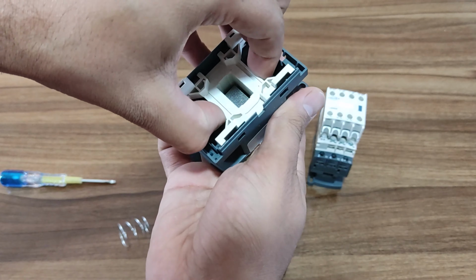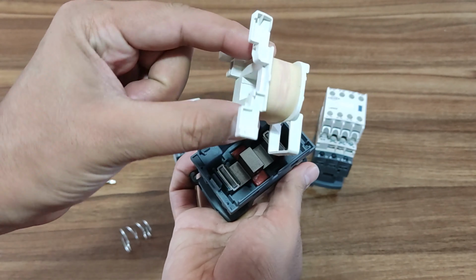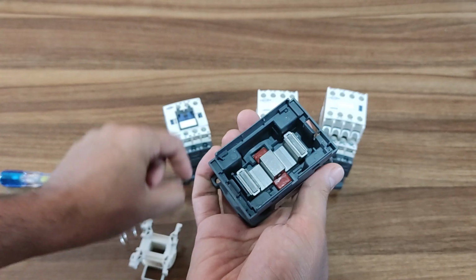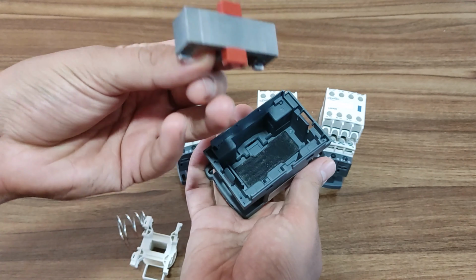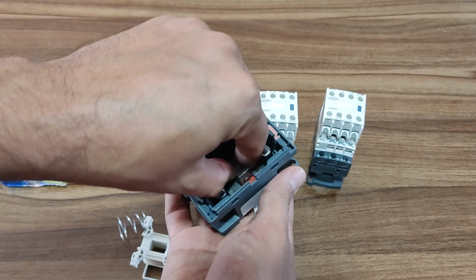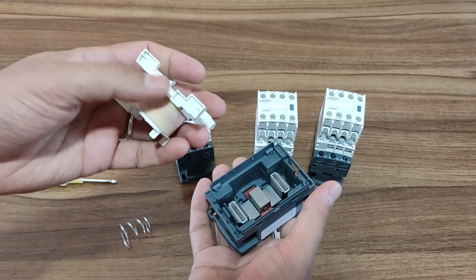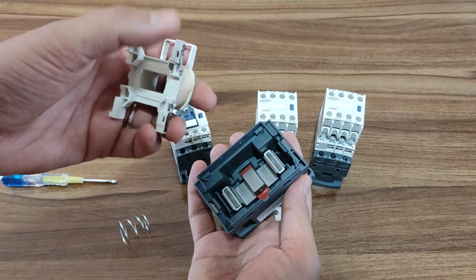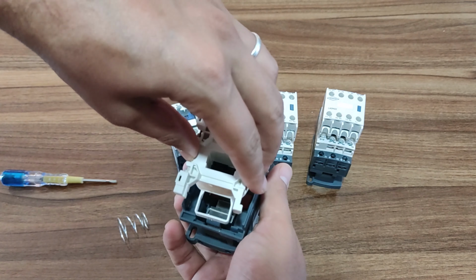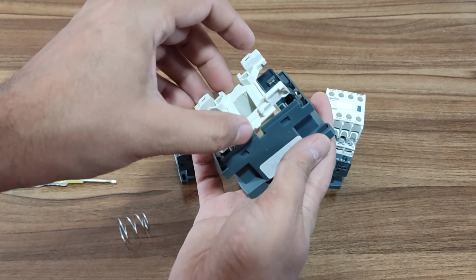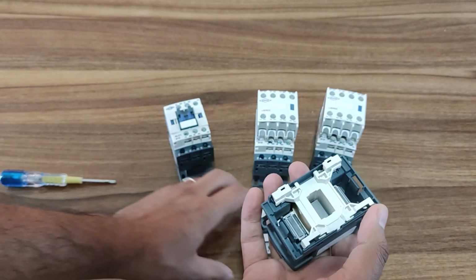Contactors are used in control circuits to connect and disconnect the consumer's power circuits. Contactors are actually the link between control and power circuits. These devices consist of two E-shaped cores, one of which is fixed and the other is mobile. Between these two cores, there is a magnetic coil or bobbin. When it is energized, the moving core moves towards the fixed core and causes a number of contacts to close